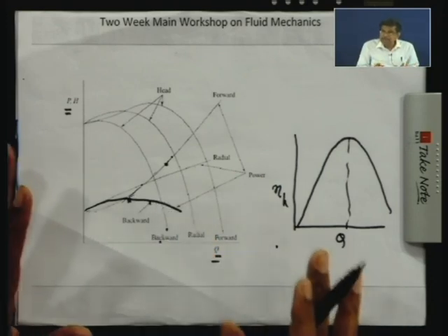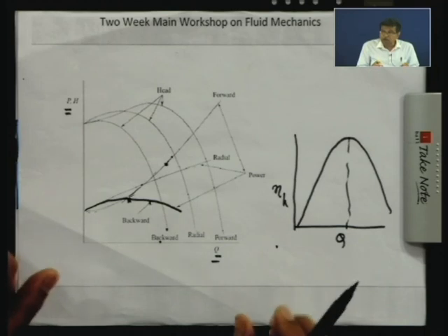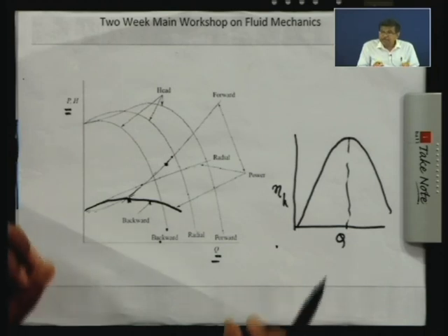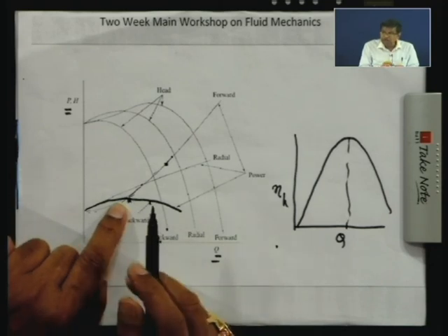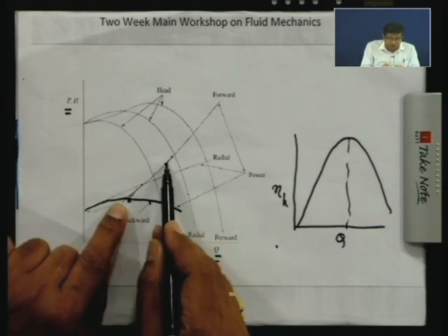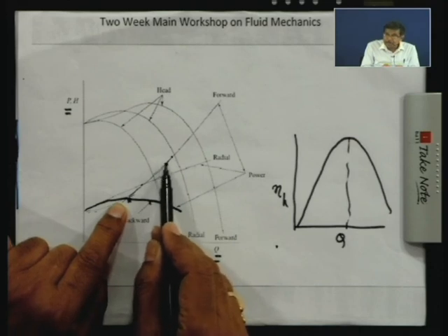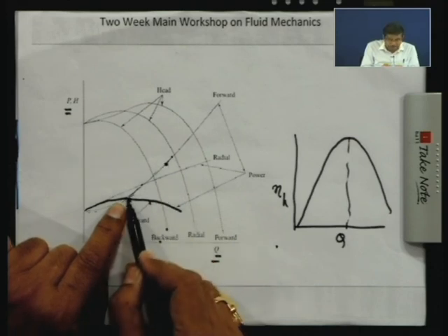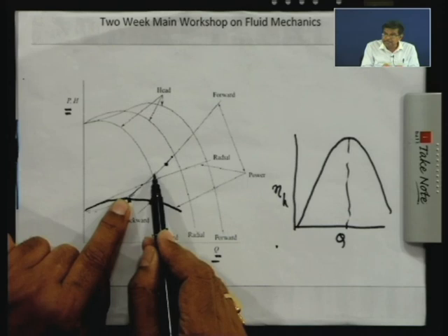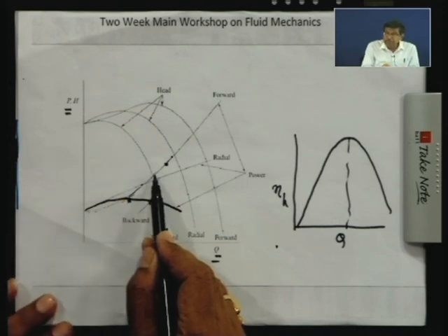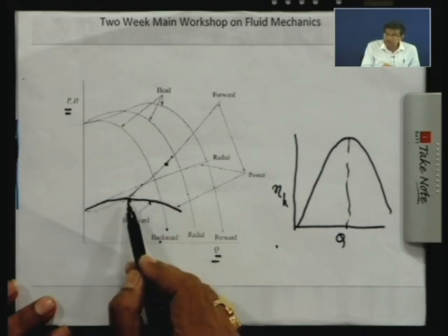That is a loss of energy. But loss of energy means that it is a detrimental thing for the pump, that it is underrated. But more risky is that if we do not rate for a very high power pump, and we rate a pump which will deliver a power corresponding to the design condition, by chance the flow rate increases, then it goes to the off design condition, and the motor may fail because it will be running under a high power for which it is not rated.